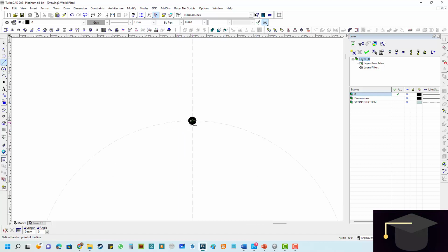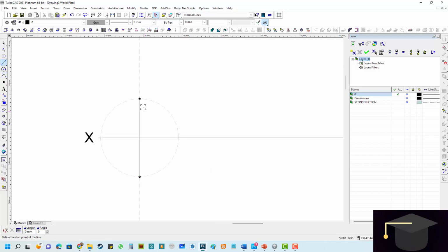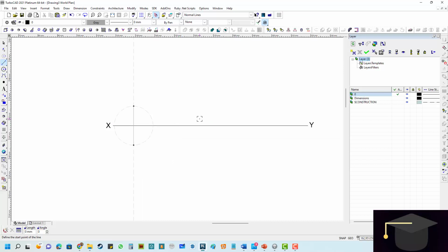that I'm going to draw on my paper, because we draw exactly the same on paper as what we do on CAD. And I'm going to just place it there and press I on the keyboard to make sure it snaps to the center. So there I have my construction line, which is my projection line from the one view to the other, crossing my XY. And you should know by now that you always have to draw your construction line perpendicular across an XY line, because the definition of an XY line is to separate views from one another.